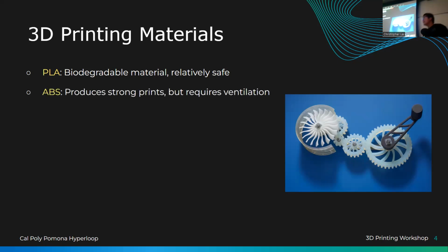ABS, oh, perfect. ABS, I don't even know what this stands for, but it's probably the most dangerous consumer electronic material that you have there. This is hazardous to your health. When you print using ABS and the plastic melts, it releases harmful particles in the air that, when you breathe them in, would damage your lungs, which is why when you print with ABS, a lot of the time it comes in an enclosure, which means there's a little box on your printer that takes the harmful particles and pushes them to another place, like outside your house, right?